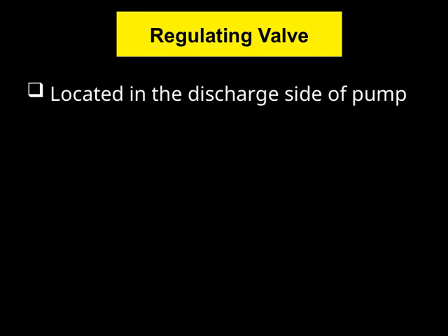Connecting this to the overall system, the regulating valve helps us fine-tune the process, ensuring smooth operation and protecting other equipment downstream. So, always keep in mind that the discharge side is where we manage flow control, making the regulating valve a vital part of the pump system.